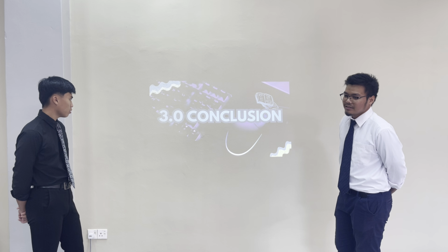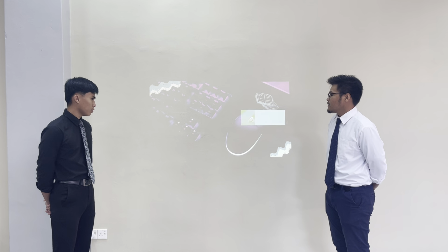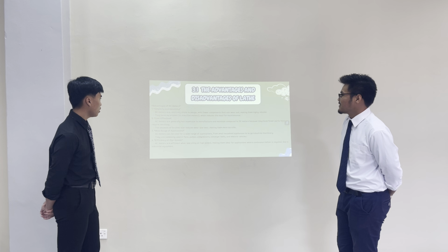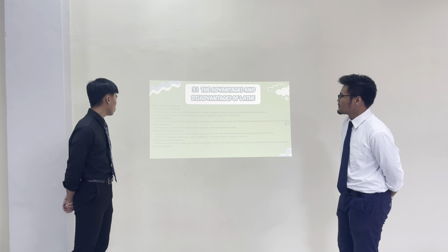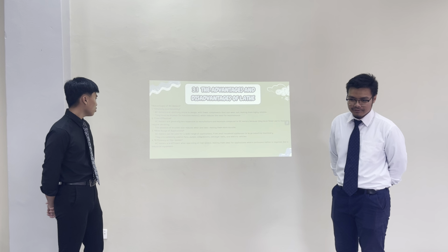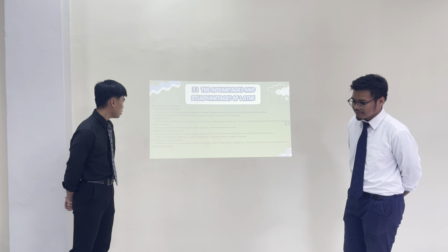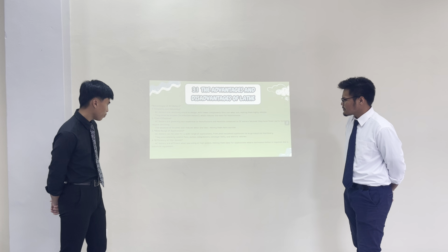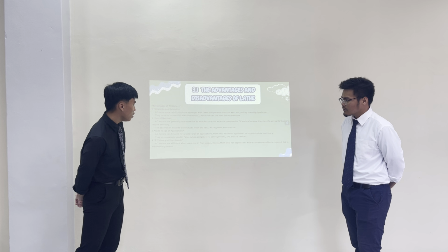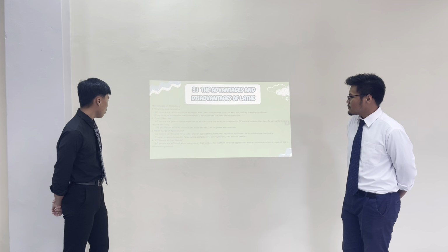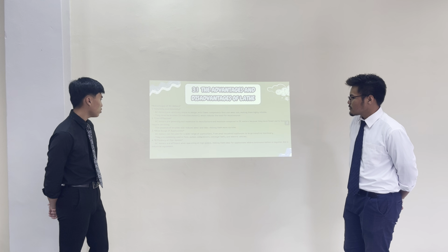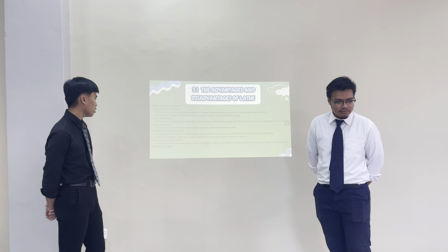Number 3 is conclusion. Advantages and disadvantages of AC motors. The advantages of AC motors: first, simplicity and reliability. AC motors are relatively simple in design, with fewer components that can wear out, making them highly reliable. They have no brushes in an induction motor. This reduces the need for maintenance.